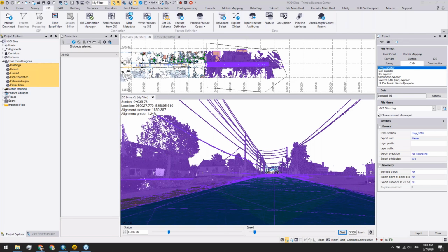Or sometimes simply because you scanned only half of the tree, TBC will still give you some result, but the position of those trees or poles can be quite off from where it is supposed to be. But in this data set specifically, I would say the accuracy ratio is about 85% or so. I don't have to do too many manual modifications afterwards.